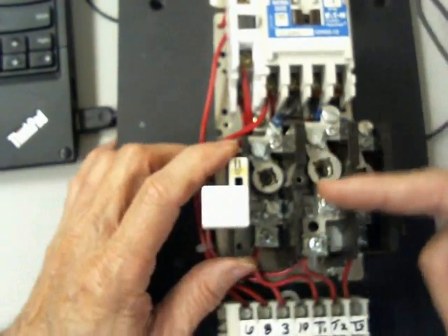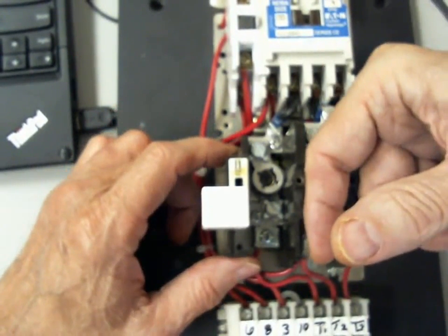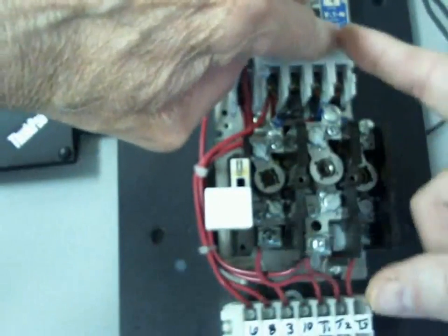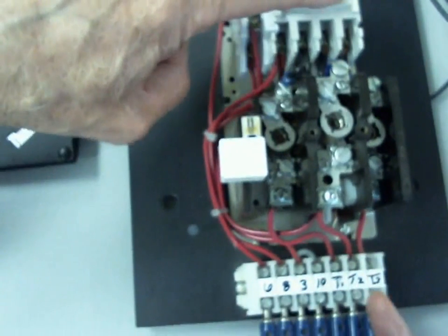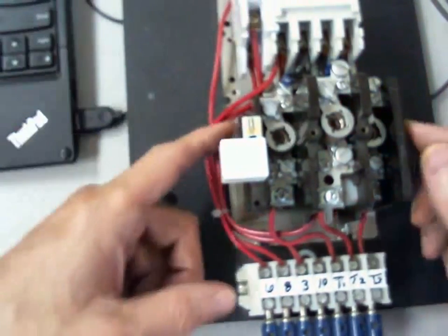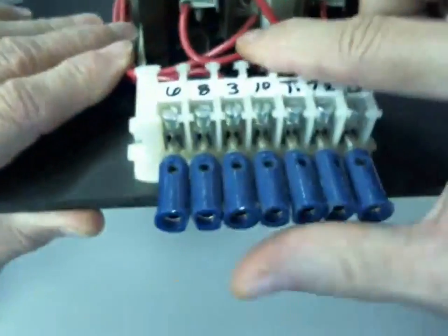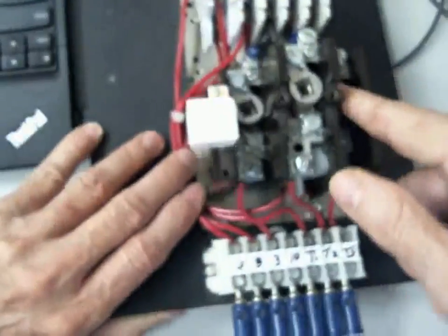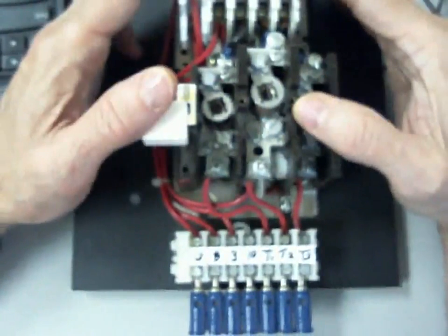So here's my overloads. So these are not the overloads. These are the sensors. Okay, so what happens is T1 or T3 is connected to the sensor. The sensor goes out to T3 down here, which is where we connect our motor. So all the motor current flows through this sensor. And then it's got a set of contacts that we'd have to find. They're right down here. These are the overload contacts right here. So if this guy here senses an overload, it opens that contact, and of course this goes back up to the relay. Y'all understand that?